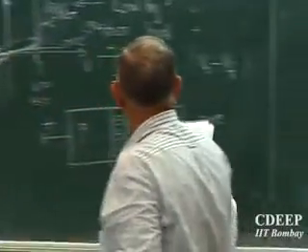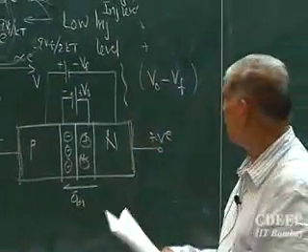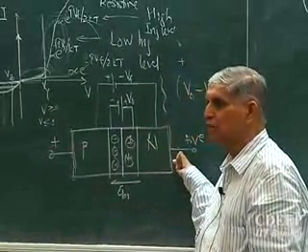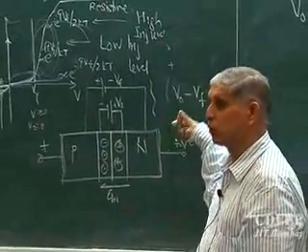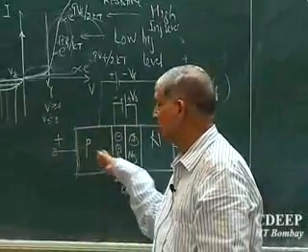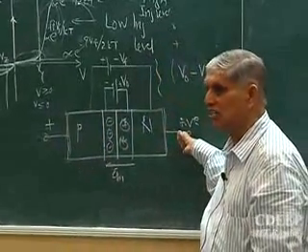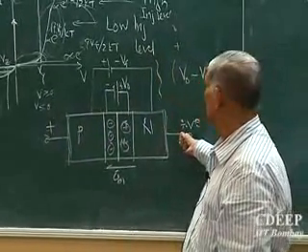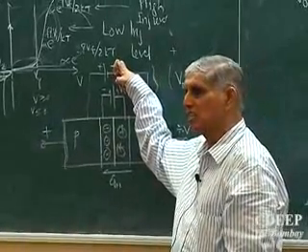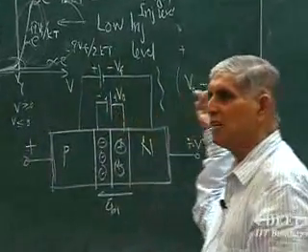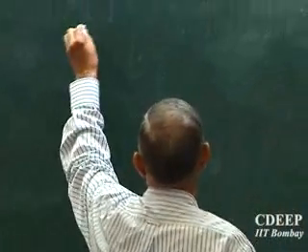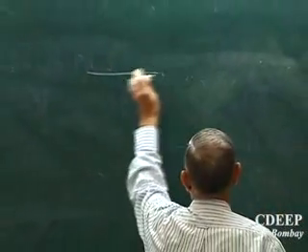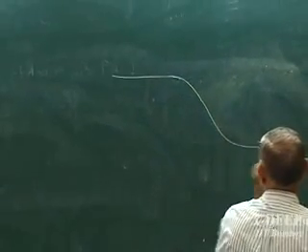So in all forward bias, even if you apply any external voltage, VF will always be less than V0. So initially what we'll say is, low injection means low voltages. We say there is no voltage drop here, these are charge neutral regions, there is no space charge here. Therefore all that voltage will appear across the junction and the net voltage will be V0 minus VF. Before we go to this, let us say this is our band.